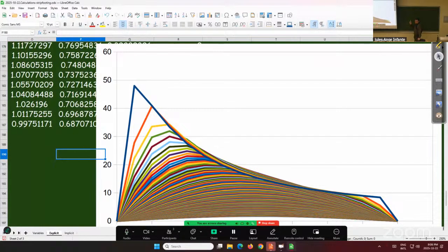So you have to keep that in mind for your design. Okay? And there will be a period of time where here, so you cannot design for this pore pressure in the middle of the clay layer. You have to design for the highest pore pressure you're gonna get. So this is one of the things that you get out of these simulations that you may not get. So even as a designer, you might be tempted to use just this pore pressure distribution. You know, for design purposes and so on, you think you are being conservative by using time equals 0 pore pressures, right?